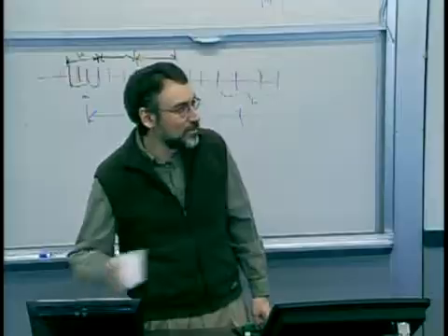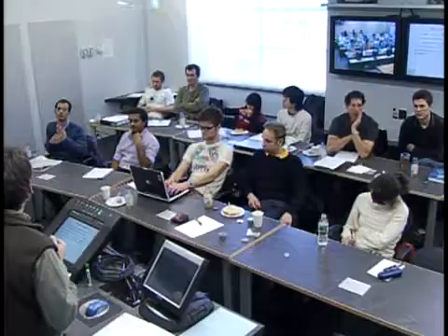If each step is Six Sigma, like you mentioned, let's say the real determinant of yield is tracking. You could have Six Sigma for everything, and you could still have zero yield because the tracking is not there. So is there like a Cp and Cpk of a tracking structure that we could create? Well, I'm not quite sure what you mean by tracking. If by that you mean, for example, being on target. Yeah, let's say length tracking between horizontal and vertical gate lengths would be very important, and each step by itself could be Six Sigma, and if the tracking is off, both could be within that limit, but yeah.